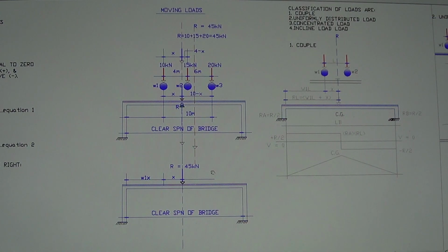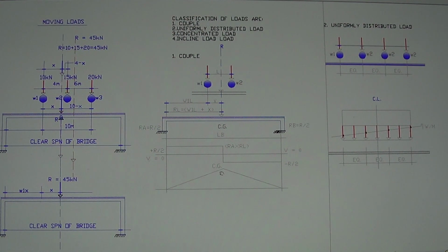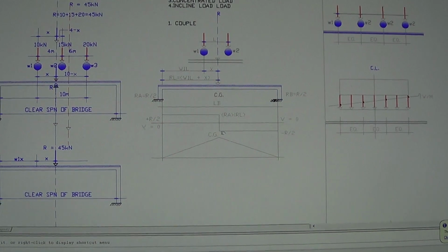So based on the position of the resultant force, you can solve the shear diagram and the moment diagram as well, the maximum moment due to this load. This is just the 2 loads. This is an example, it's the same as this one because of the resultant being 1. This is the layout for the shear diagram, and this is for the moment diagram. The moment here is PL over 4. Alright, so we're going to derive that later on.